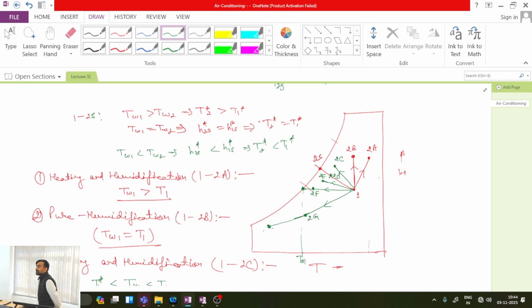For removing that heat, typically we study that we use ambient water, lake water or something. Many times it is given in the question that we are taking water from the lake at a certain flow rate. So wherever I have a water body close to the thermal plant, it's very simple. You take water from the river, exchange heat, and then again dump the water into the same river.